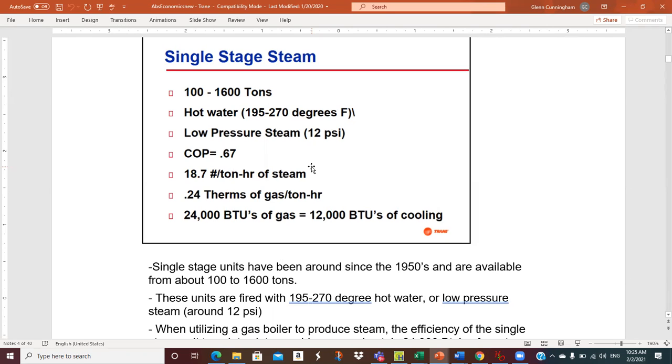So that would say that my input energy in BTUs is 17,757.52. So I'm going to store that away. Now, let me calculate what I get based on this for the COP. If I take 12,000 and divide it by that 17,758, that should give me the COP, right? Because that's cooling effect divided by energy input.